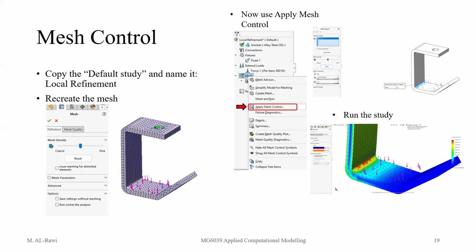So do you see that? Now we use a smart way to get better, enhanced results with less time, less energy on the computer and the processor and everything. For me it comes to 139.73 megapascal, but for you it will come differently. However, the fine mesh study shows 141, so we got even better.